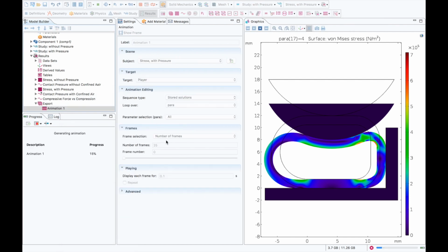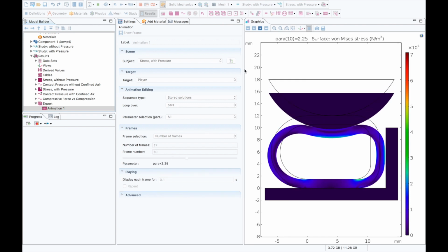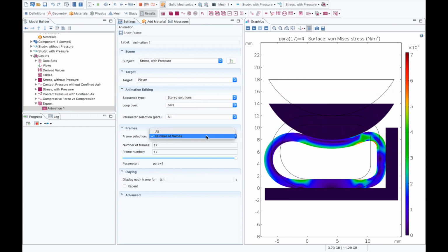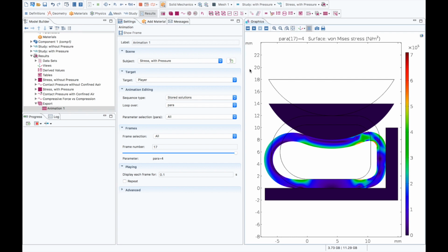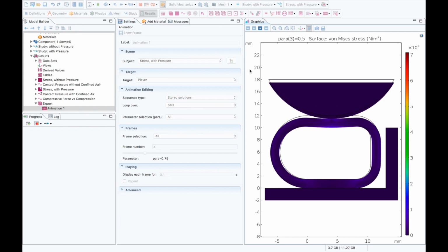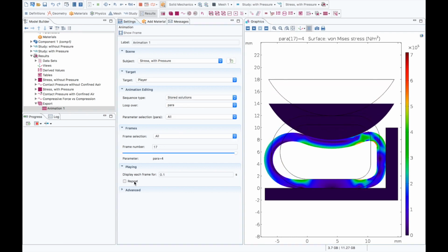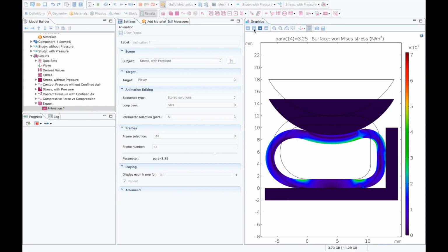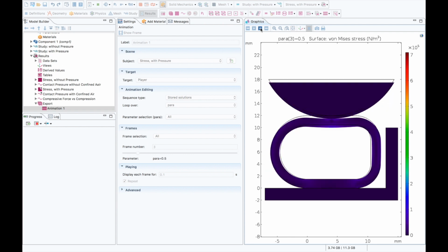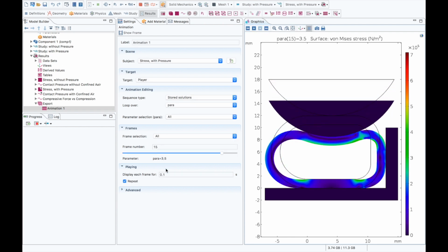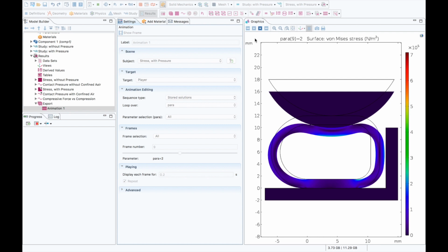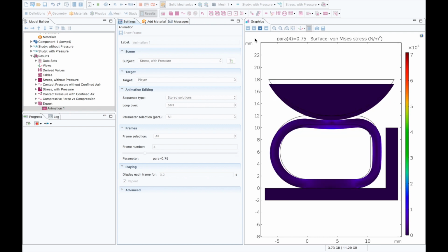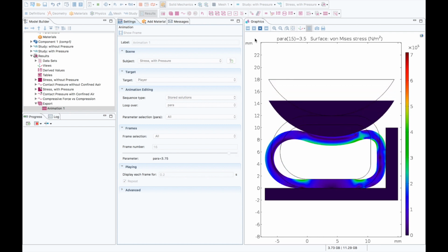So you can include all your solutions and you can loop it and you can export it to any presentations if you would like to see this. So this is one little example of how to define hyperelastic material models, but there are also other material models, not just this one. You can have several other models that you would like to use. These are the predefined interfaces for them, and as always you can use a user-defined one, so you can include your own material model quite easily.